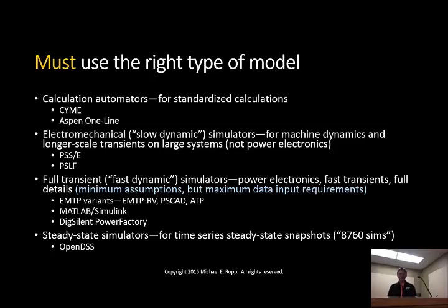Then we get to the full transient dynamic simulators. And this is the kind of simulation we do. We actually do PSSE as well, but most of what we do, our main workhorse is MATLAB Simulink. We also use a bunch of different variants of EMTP. What these simulators do is they actually are looking directly at the differential equation representation of the system. So in theory, this is supposed to be the most accurate, least assumption physical model of your system. Then the different programs have different solvers that they use to execute the thing in different ways.